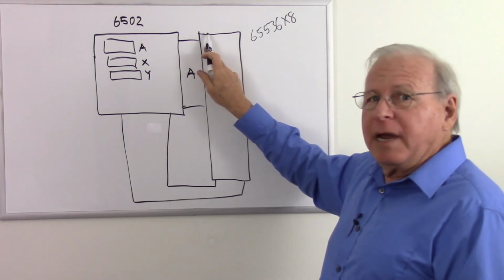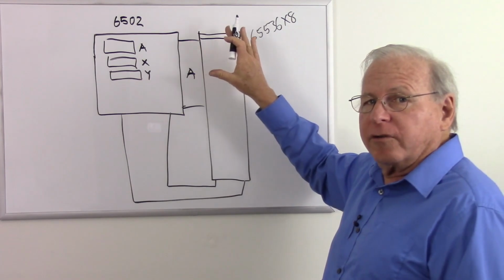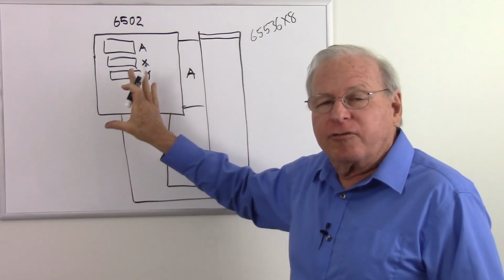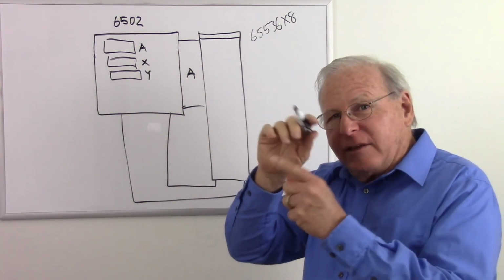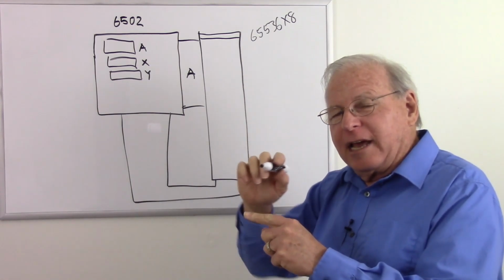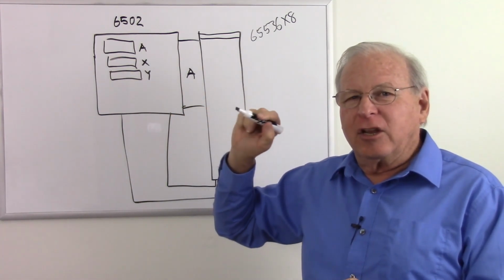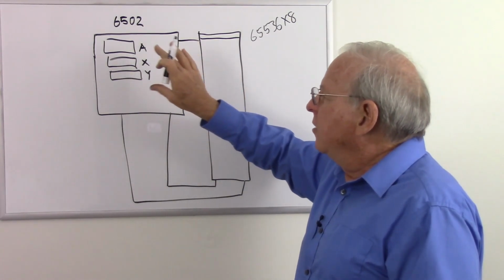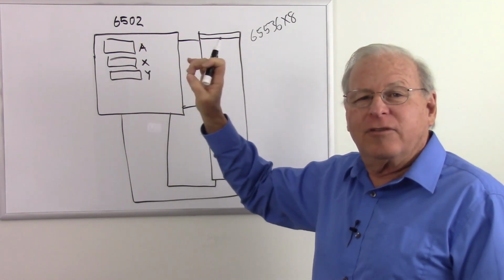It could go to memory and pull out 8 of those bits of memory, 8 of those ones and zeros, which we call a byte, and it could store it into a place called the instruction register, and there's some circuitry in there that would decode that, make these voltages go here and there, and then finally come out with one wire with a voltage on it that said, go through this sequence of operations. And so these instructions say, do this, now do that, and now do the other thing. Let's take a look at the things it could do.